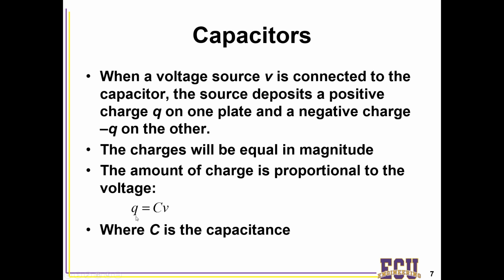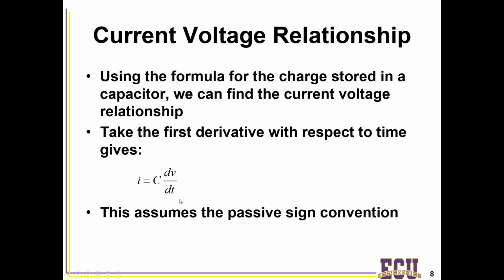in time. So if we take this equation and take a derivative of both sides with respect to t, where charge could be changing with respect to time, voltage could be changing with respect to time, and your capacitance is a constant, what you get is dq/dt, better known as I, or the current, equal to C, that's a constant, times dV/dt. This is one of the most important equations you're going to remember whenever you're analyzing any circuit that has a capacitor: I equals C dV/dt. This is a first-order differential equation that expresses the relationship between current and voltage.